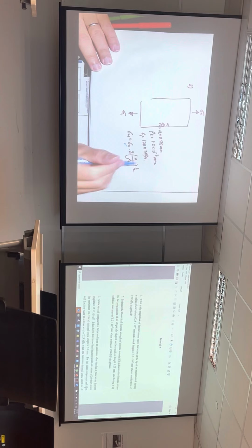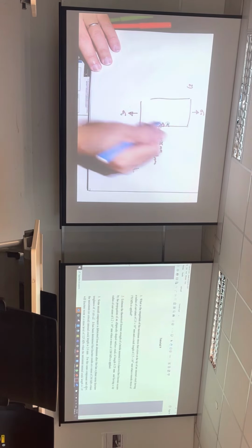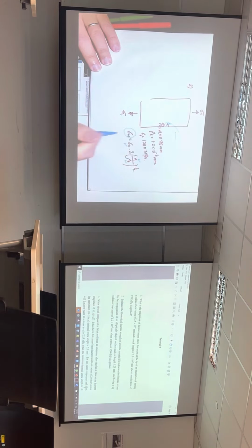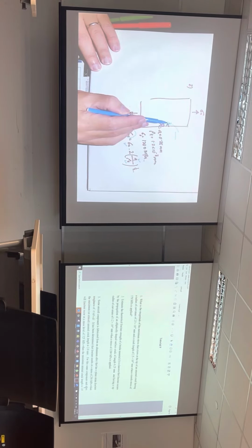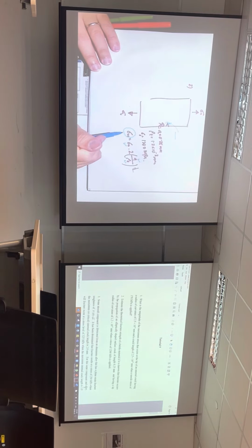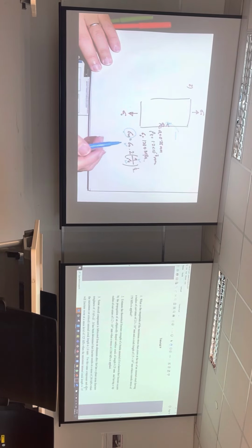You have this one, you have this one, you can find this one. So basically, given all these conditions, when I apply this, this thing fails. At this point in time, my sigma m here is this particular value that I've calculated. This is the maximum value that causes the thing to be unstable, and the crack will initiate and go off. So what you're trying to find is the sigma m at the crack tip, the value where this becomes unstable. This will be your theoretical strength.